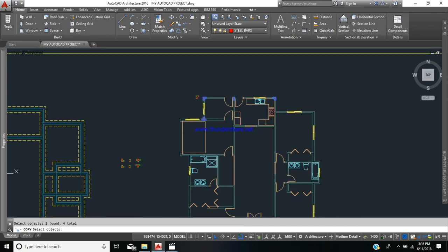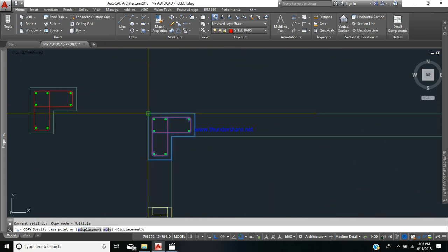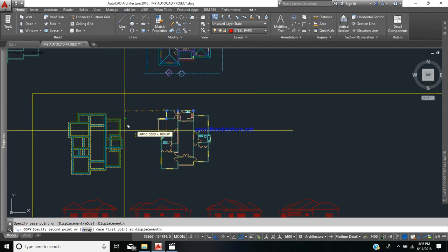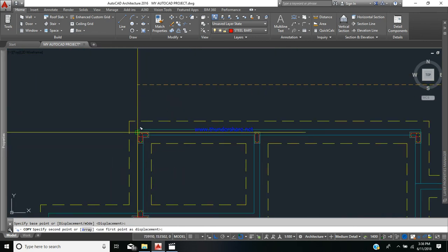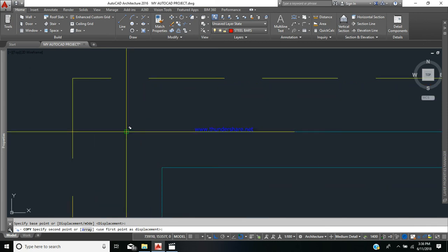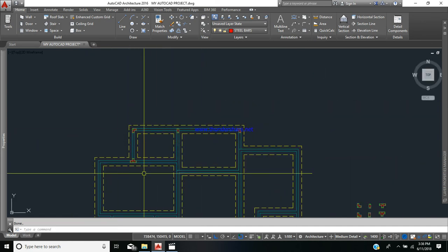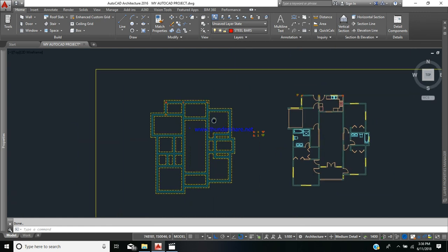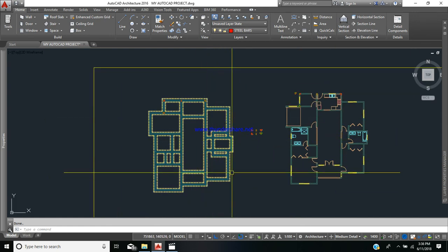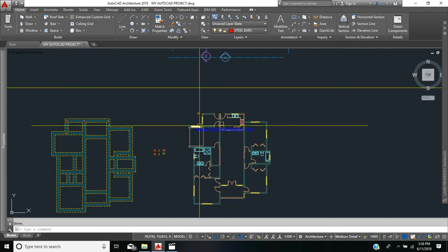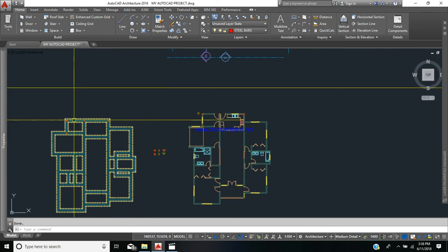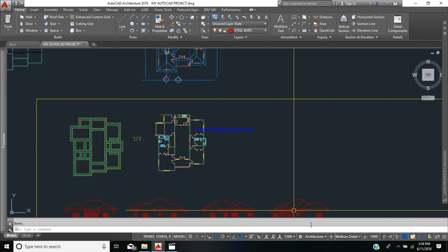And so you would have done the entire selection, give an enter, and perhaps you would wish to hold it at this intersection and paste it at this matching intersection. Ensure though that the snap is at the exact point that you would want your insertion being done. Alright, when you give a click, all your stiffeners would have been represented in your foundation plan. The remainder of the wall, however, would have to be hatched, but we will discuss that at another time.